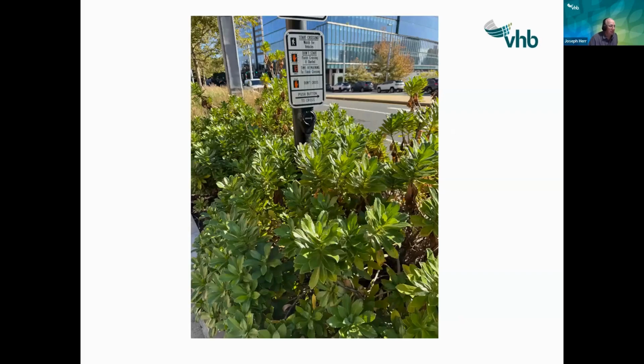This one just happens to be a miss by the agency. I don't know the backstory on it, but I can imagine when it initially got designed, there probably was not a vegetation on the bottom. This planting area with the curb and the dirt was not there. So I'll bet another project came in. They added the curb, they added the landscaping, not taking into account that you needed access to this ped button. It is still that way today. You don't have access to it. And a lot of times what happens is when there's something done after something's been accepted and it's been out there for a while, that you run into issues, in this case with the ped button.